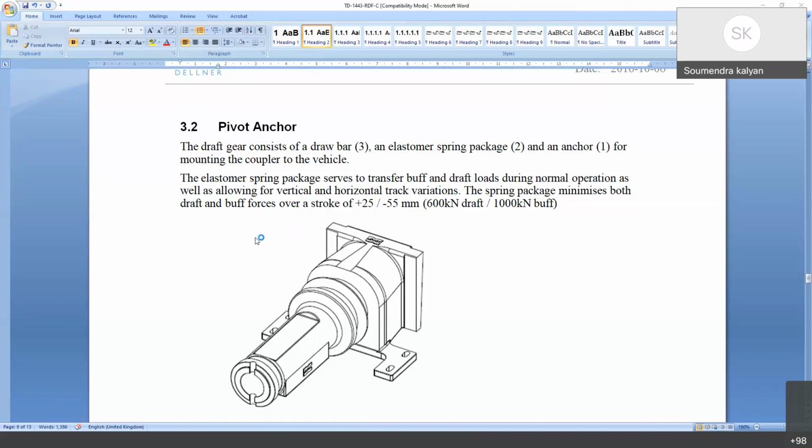In case of derailment, I don't think it will be different with respect to any LHB coach. Maybe during derailment, the coaches here are more rigidly coupled because of the flexible gangway and the semi-permanent coupler. The chance of toppling of the coaches will be less. But if one coach gets derailed, a few more coaches may get derailed.